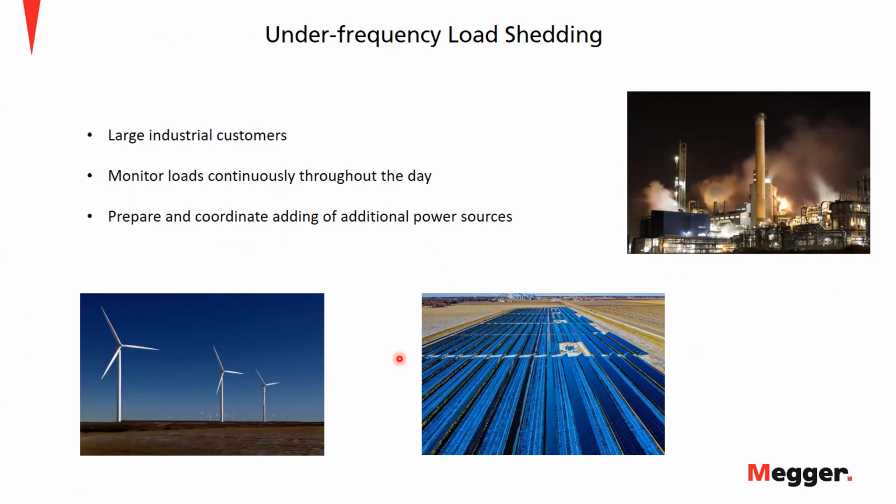What we try to do is come up with some type of lease or program where the industrial customer will get a specific rate, and they get a good energy rate to have this under frequency load shed protection placed on certain substations in their group where they're bringing power in from transmission lines or some other feed or source that they have. So they do get pretty good rates for that as well.